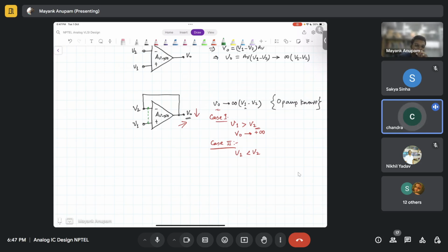So in a more complicated circuit with many nodes, for example circuits with multiple feedback loops, say at three or four different points, the potentials are somehow equal. Can that also be considered a virtual short, or is that a different case altogether? It's applicable only to two points which are very specifically related. A virtual short happens when two node voltages are always equal to each other, which is enforced by some kind of circuit mechanism. Then you can say it is a virtual short.